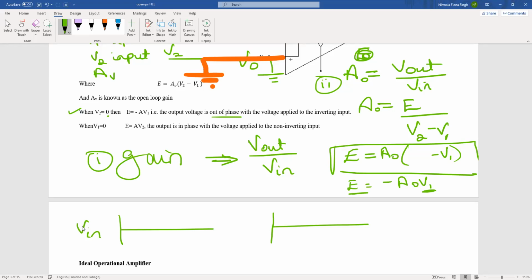So if our input voltage looks like this, a nice positive signal, even though it's AC, meaning it started from positive, your output signal will be the complete opposite of this, and you're going to get this instead. So that's what we mean by an inverting or completely out of phase output, where you get a 180-degree flip from your input to your output. See this little piece here? This is like what you get in multiple choice. So that is for the first one.